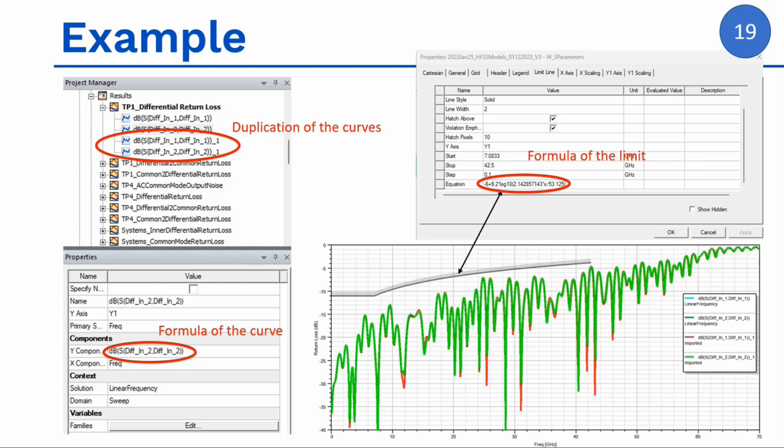I would advise you to download this template, even if you are not doing stuff like that, because you're going to learn a lot from the formulas that we used to calculate many curves. There are others that take multiple steps to calculate. You are going to be able to see them too. We describe them in detail in our template. Not only that, you're also going to find the limit line. So this template is, as I said, for the 802.3ck standard.